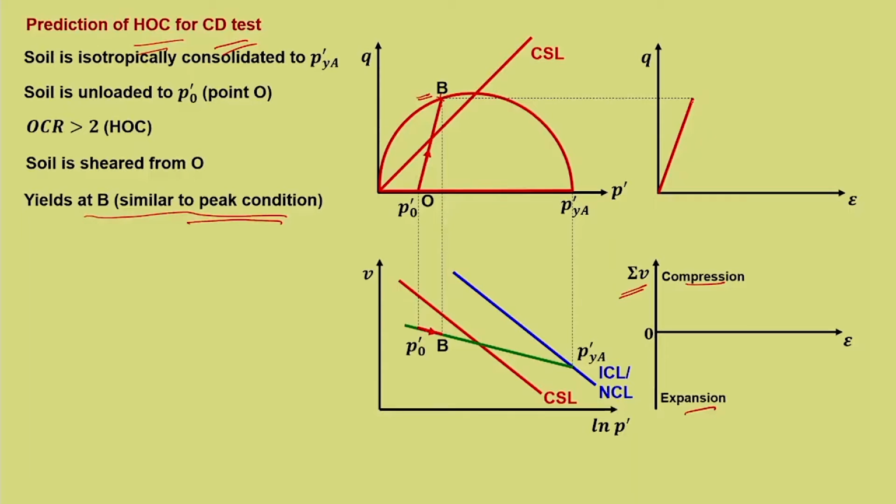But according to the explanation of the critical state model, specifically MCCM, what we are dealing with now, it states that the soil will yield at its peak. So, this is a kind of idealization one has to keep in mind, and hence up to peak the response is also linear. This is also an additional condition that gets imposed because we are considering a critical state framework. So, you need to understand that many things get idealized which may not be the same in real soil behavior.